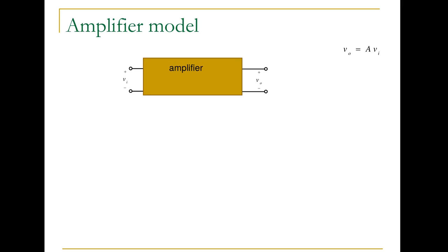For electrical measurements, oftentimes an amplifier is necessary, either to boost the signal from a transducer or to change the output impedance. What's meant by output impedance? Well, here's a picture of an amplifier, and you can see the input impedance and the output impedance.